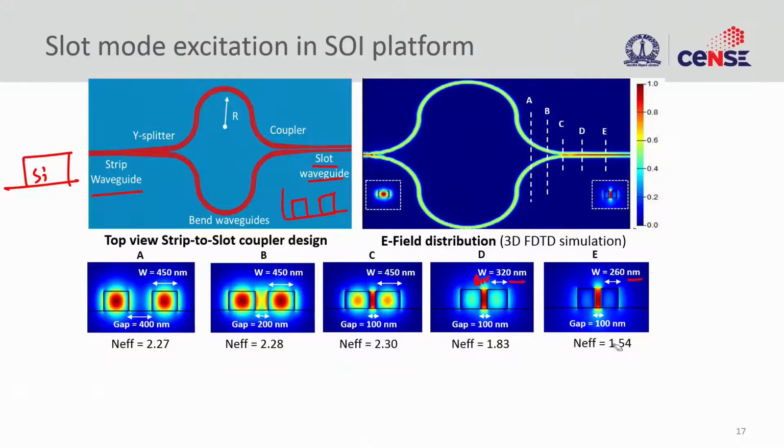but then putting these two cutoff rails together, you create a propagating solution, right. So there is a continuity equation that you need to make sure: epsilon 1 E1 should be equal to epsilon 2 E2 between these two systems, and once these two E fields are equal, right, when the E fields are together in that boundary that you have, then the energy just jumps into this cavity or into this trench that you have. So then you can effectively use this confinement, and let us look at how efficiently we can couple this to the waveguide.